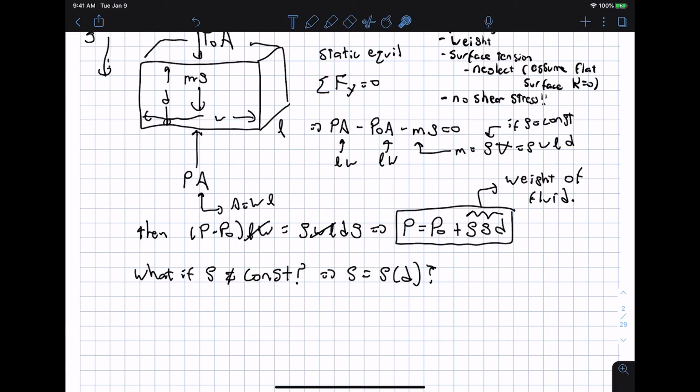Or if you're an aerospace engineer and you want to understand the forces applied to a tank when an aircraft is doing a very high-speed banking turn, there's going to be an acceleration field that is applied to the fluid in the tank, which is going to cause it to sort of bunch up at one corner here. And while it's banking that corner, it could be in static equilibrium, which means you're going to have different accelerations at different points.